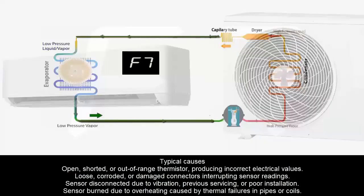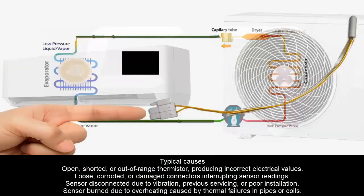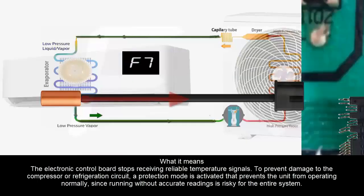Typical causes: open, shorted, or out-of-range thermistor producing incorrect electrical values; loose, corroded, or damaged connectors interrupting sensor readings; sensor disconnected due to vibration, previous servicing, or poor installation; sensor burned due to overheating caused by thermal failures in pipes or coils. What it means: the electronic control board stops receiving reliable temperature signals. To prevent damage to the compressor or refrigeration circuit, a protection mode is activated that prevents the unit from operating normally, since running without accurate readings is risky for the entire system.